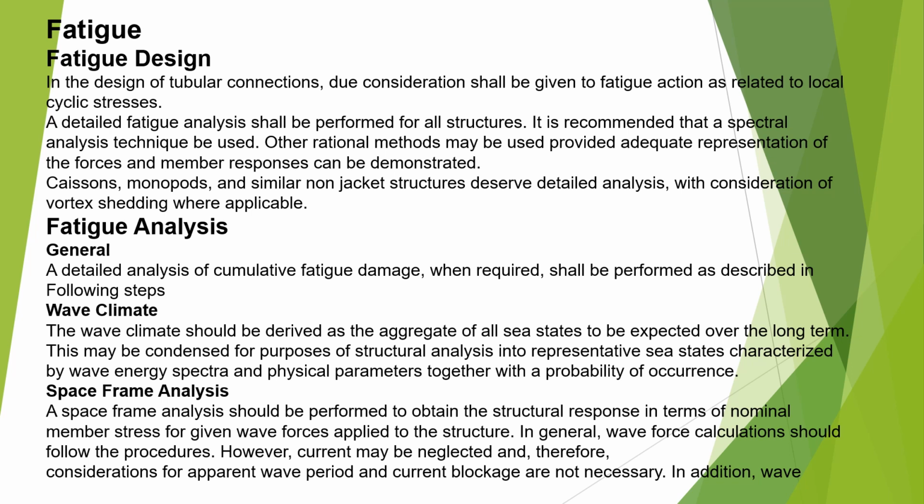Here, one thing we should understand is that wave forces should follow the procedures. Current may be neglected. In the space frame analysis, we could neglect the current. So if we neglect the current, apparent wave period and current blockage factor are not necessary. Space frame analysis, we are doing it to obtain the structural response in terms of nominal member stress for given forces. So structural response means nominal member stresses we get for the given wave forces applied to the structure. Once you apply the wave forces on the structure, it will respond in terms of its nominal member stress.